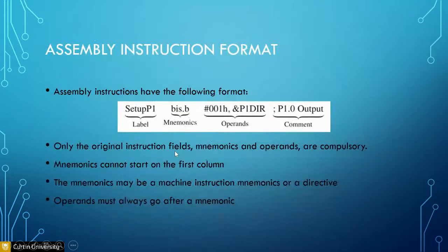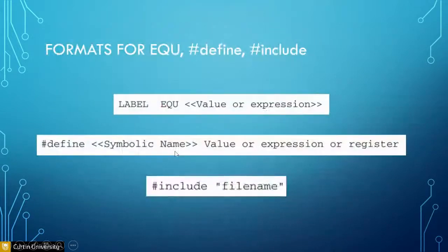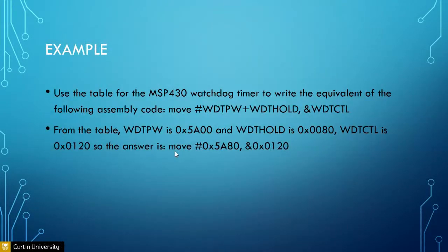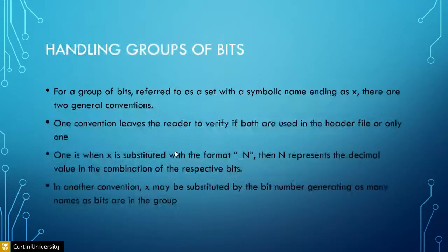So the watchdog timer, if you're not using it, bring it to reset. Again, if you're developing an embedded system for data logging for a rural area, this is very important.